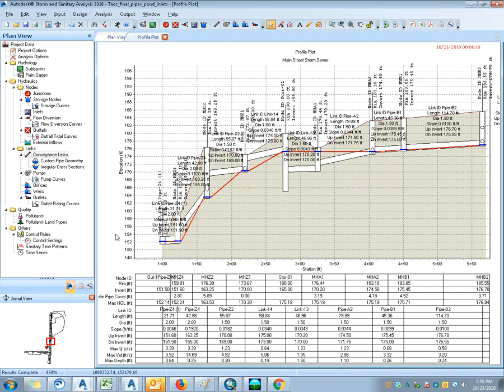Like, you design for 10 years. So we made an agreement, the county with the developer, say, that we're only going to make you pay for a 10-year pipe. Well, from my engineering standpoint, that's fine in a lot of subdivisions, but at some low points in the county, I'd really want to see what happens in a 100-year storm. And this does it. Nothing else really does.